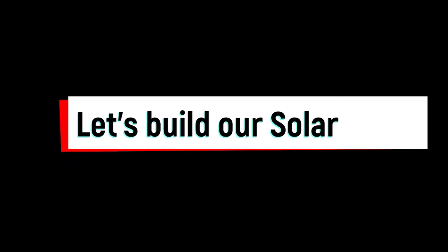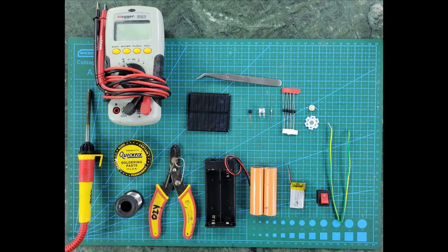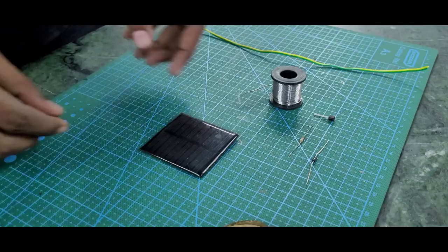So now let's build our own solar lamp. Now we have the components required: multimeter, soldering material, stripper. We need two rechargeable lithium ion batteries, or you can take one battery as well, 3.7 volt. We need a transistor, NPN BC547 transistor. We need a 10 kilo ohm resistor. We need a diode, LED, switch, and a couple of wires or cables.